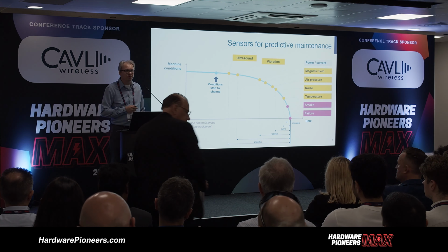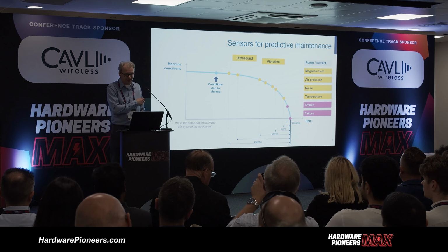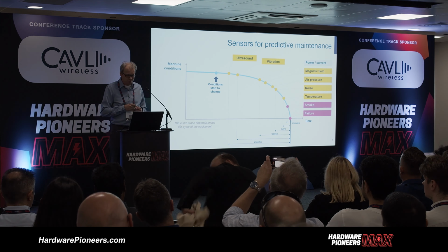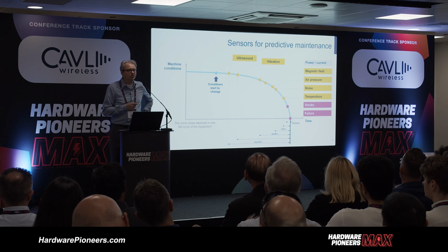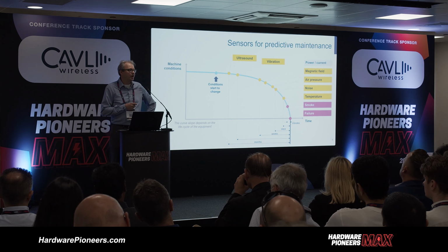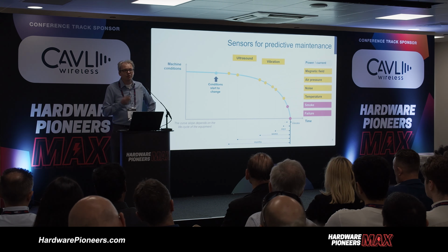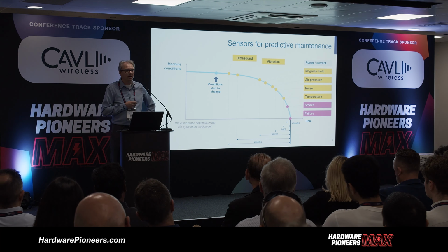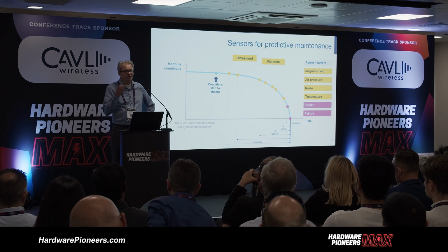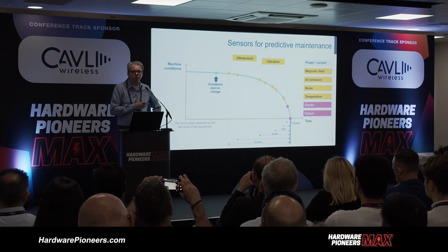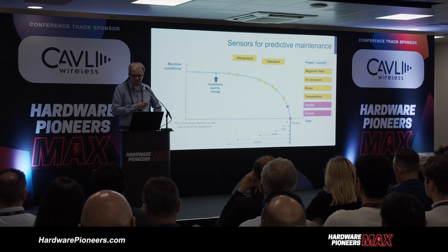Then measuring power and current would be the next step. Then, for example, measuring the magnetic field on top of the motor. Then in some applications, for example anything related to air, it's better to measure the air pressure instead. Then at some point, these devices really start to make noise, and also their temperature starts to go up. And then eventually, you end up in smoke and failure, which you for sure want to avoid.